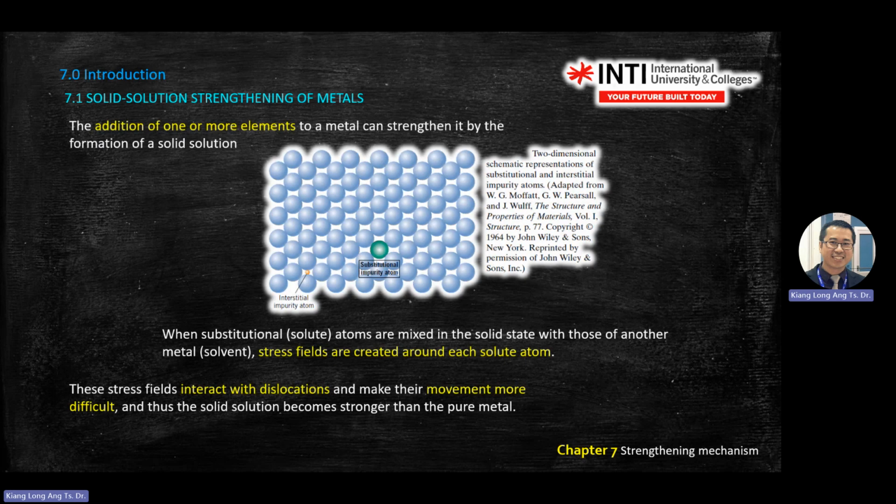Okay, then on the mechanical explanation of strengthening, when you put in all this impurity, either interstitial or substitutional, the main purpose is to resist the movement, because you add more things in the space there, so that it makes the host or solvent harder to move around. That is the mechanical perspective on why or how you strengthen metals. We are now looking at metals.